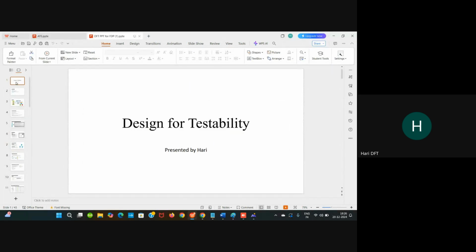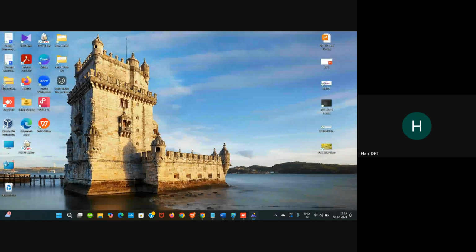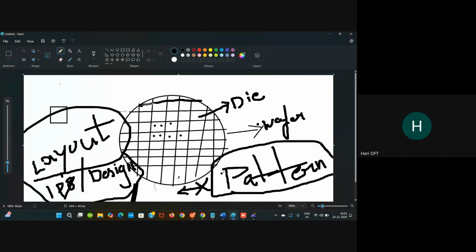For the testing procedure, listen to me. There will be a separate equipment called ATE, automated test equipment. ATE engineers who work on this scenario will collect the pattern. Soon after the fabrication, the client asks DFT engineers to deliver the pattern.